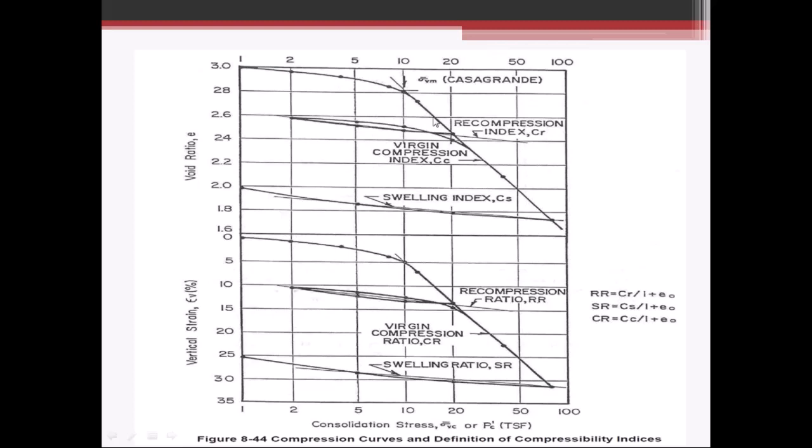Most geotech textbooks out there will have the formulas and the guidance on evaluating these curves. Sometimes it's difficult to determine this past pressure where the curve breaks. Sometimes in the laboratory we don't see that break, which could be something with the soil itself, or it could be from sample disturbance. So those are things that the engineer needs to evaluate when you're looking at that data.